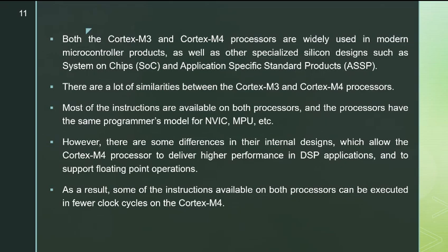So, both the Cortex M3 and M4 processors are widely used in modern microcontroller products as well as other specialized silicon designs such as systems on chip (SoC) and application specific standard products (ASSP). There are a lot of similarities between the Cortex M3 and Cortex M4 processors. Most of the instructions are available on both processors, and the processors have the same programmer model for NVIC, MPU, etc. However, there are some differences in their internal designs which allow the Cortex M4 processor to deliver higher performance